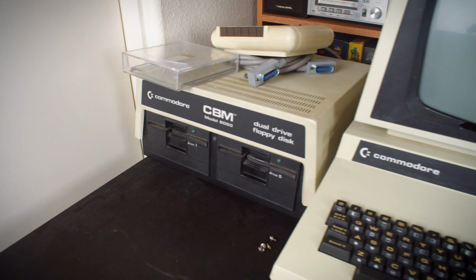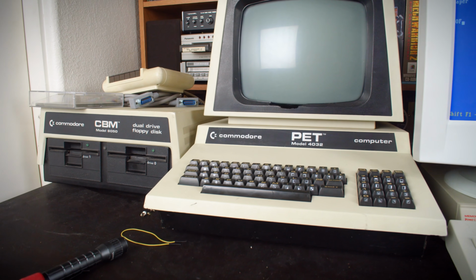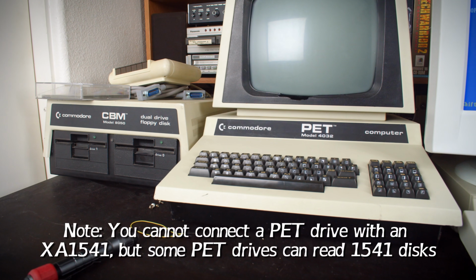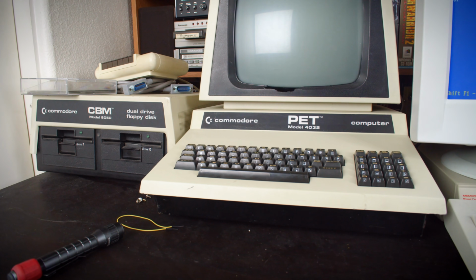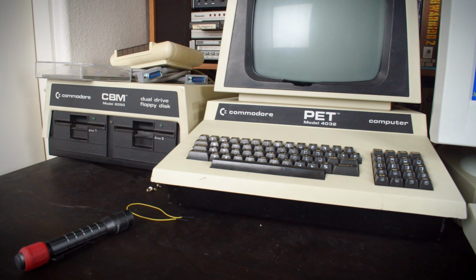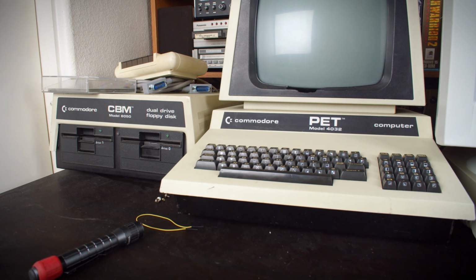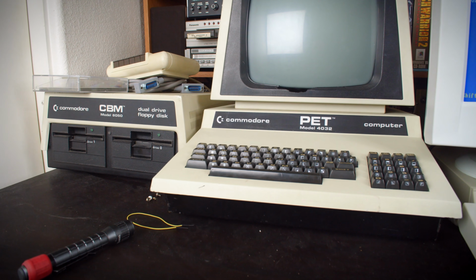And one other thing before we get started, if you want to use this for a PET, like I did, then you need to make sure you have a compatible floppy drive. Now, the floppy drive I have there is not compatible, and I didn't know this until after I made the cable. So you need a 2040 or a 4040 drive, not an 8050 drive like I have here. It's like tracks per inch or something that's incompatible, but the physical layout of the information on the disk is just not compatible with a 1541 drive, so you're never going to get one of those to work.